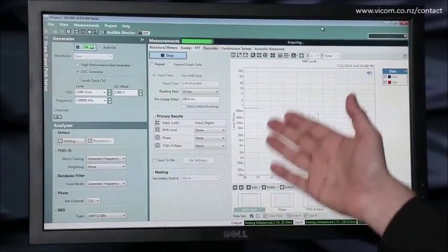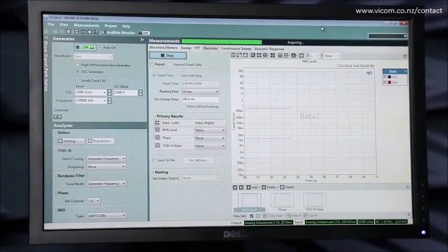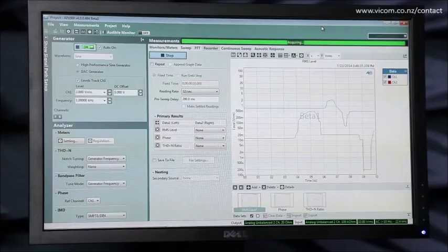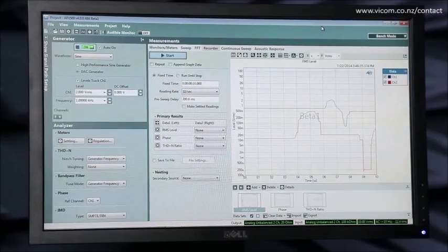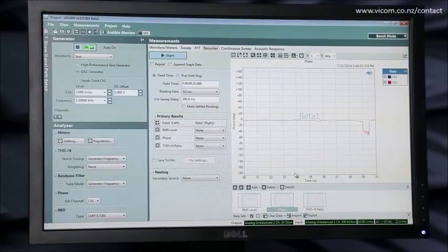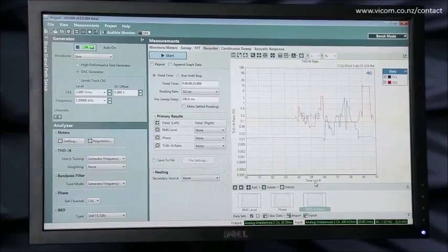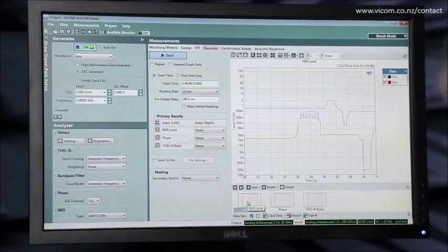And so we are measuring the RMS level at the output of the mixer. And if I change the gains in the mixer left and right, you can see how the RMS level will change over time, as you would expect. So there's a 10-second recording where I was just varying the levels. Now we can have a look at how the phase changed. Well, the phase changed a little bit like that, and here's how the THD changed, kind of went all over the place. That's to be expected. If you're making big variations in level, THD is naturally going to do that. But so we can see how things vary over time.